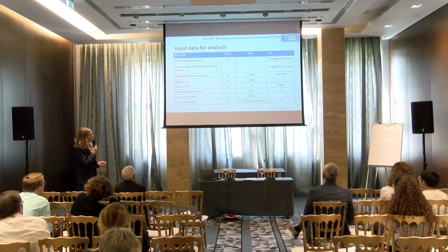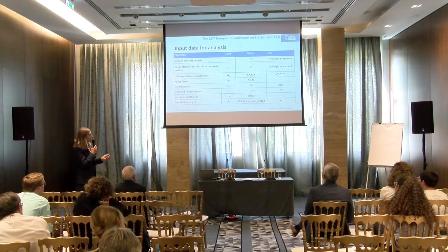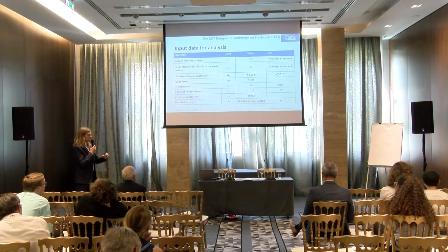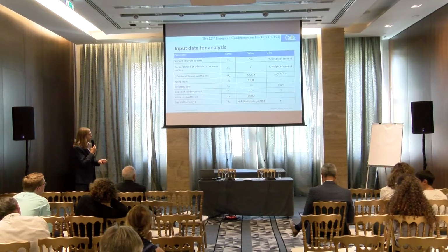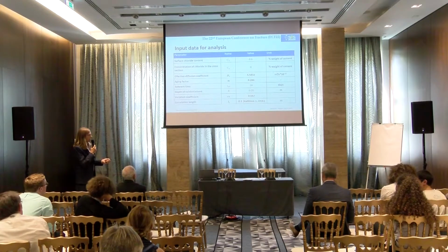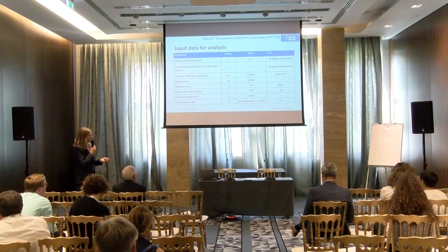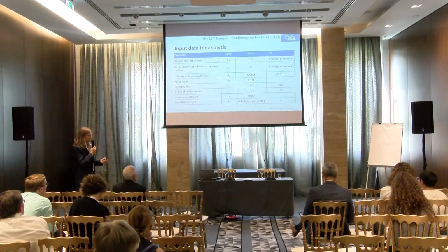Here are the random input parameters. So the material property is the diffusion coefficient. Since the concrete improves its property over the age, over the time, due to the chemical process of hydration, here's the aging factor, and the variation coefficient of the material property is given here. And what is most important, the correlation length that controls the spatial variation was adopted based on the suggestion here.